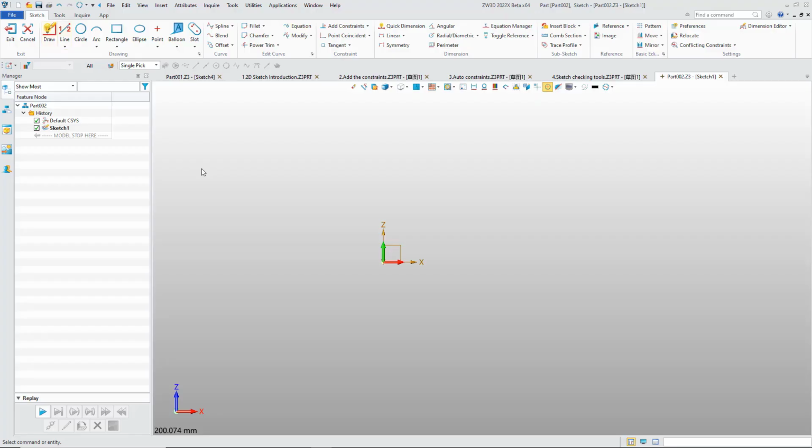You can find the Draw tools from the Sketch ribbon tab. Click it, and if you want to draw a line, press the left mouse to select the two points. If you want to create a semicircle, select the Draw tools, use the left mouse to select the first point, and press Alt to select the second point. After that, loosen Alt and click the second point again. You can create a semicircle.